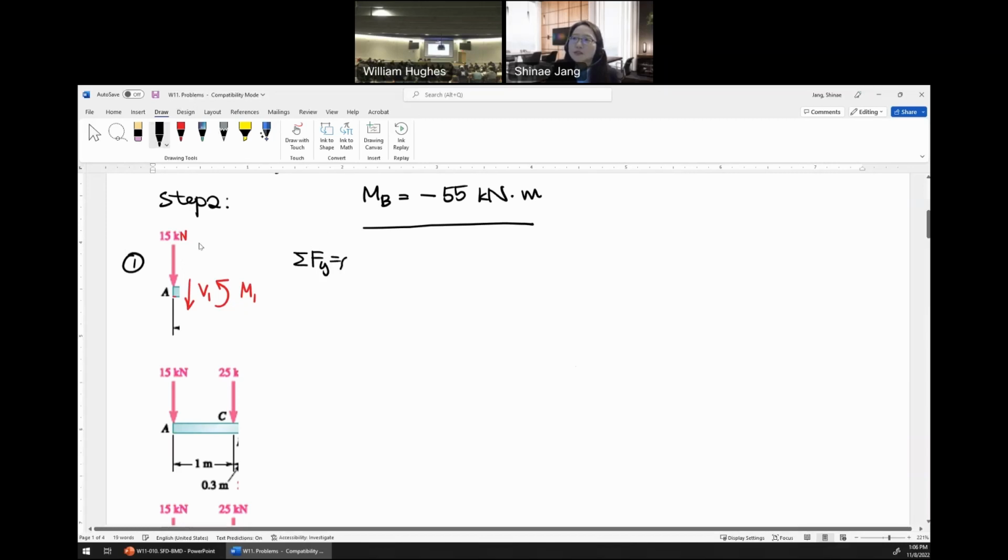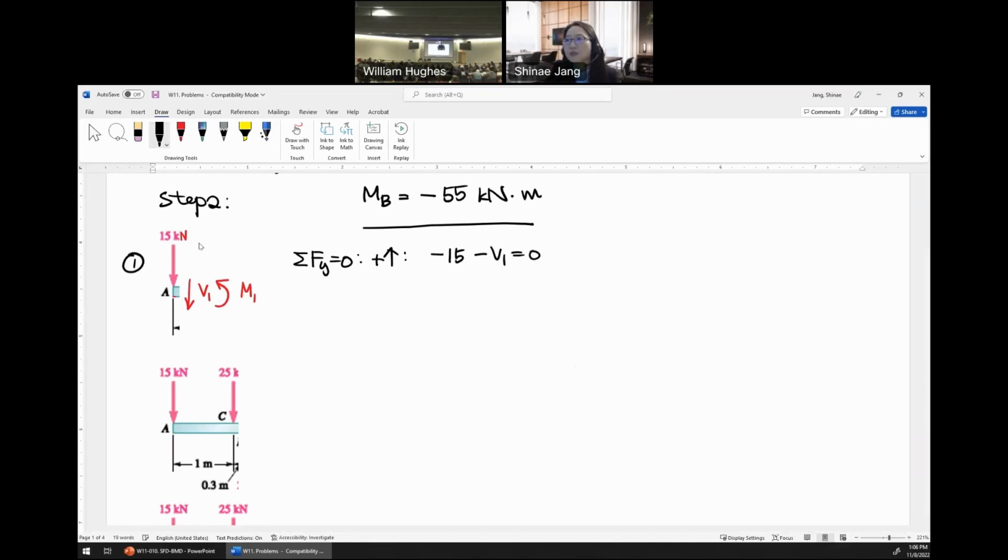So Fy first, we will not solve Fx because it's trivial. Fy equation, upward is positive. It's so simple. We have 15 down and then V1 down. So V1 is minus 15 kilonewton. So I speed up and I upload everything. So yeah, don't worry about class notes. Please follow me instead.